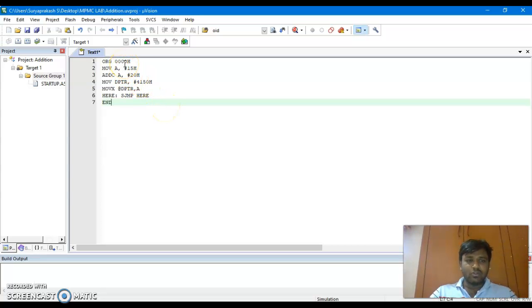In this program you will see what has been added as ORG, that is the initial level of the memory from where the program has to start, because there will be certain code that will be loaded in certain program memory, and we need to select only the user accessible memory.